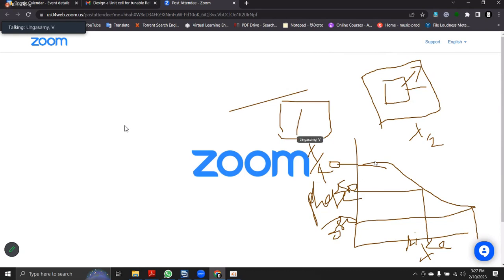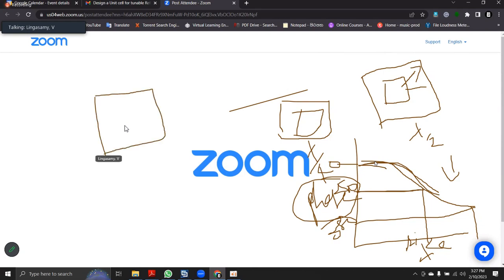So if you use lambda by 4 size, this problem comes: the entire dynamic phase range reduces basically. But if you want to improve this for lambda by 4, you can use, for example, multiple dipoles or complex structures. Many structures are there, like this kind of structure. That will give you the required phase range basically. Even here also, like this, you can achieve that phase range.